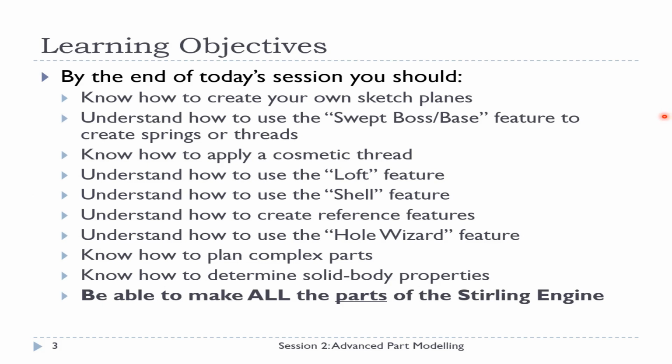Today's learning objectives, so hopefully by the end of this session, you will all have knowledge on how to create planes or different reference geometries on SolidWorks. We will be discussing the swept boss base features, and we'll discuss how this feature can be used to create springs or machine threads.